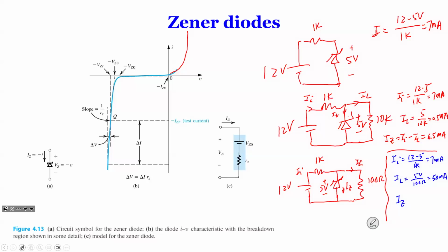So then how would you do this? Well, the idea is that we're going to do it as a voltage divider. Let's call this VL. So VL is going to be 12 divided by 1K plus 0.1K, times 0.1K. That gives you how much? 12 divided by 12.1. It's almost 12. So it's very small, less than 0.1 volt.